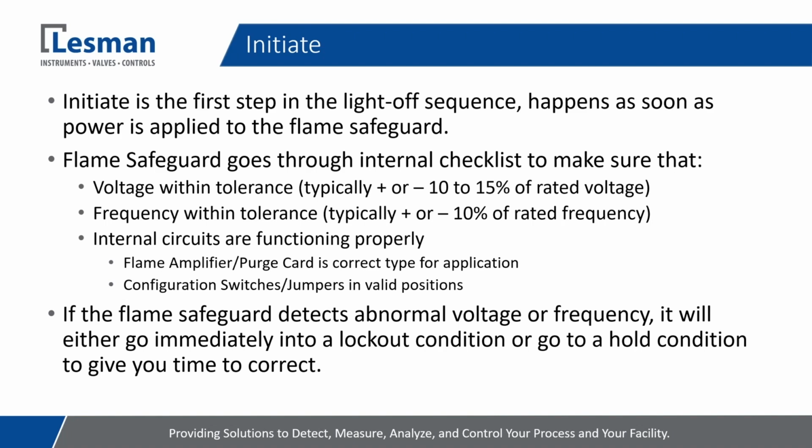With the Honeywell 7800 series, as well as some of the FireEye and the other flame safeguards, you have plug-in modules that you would insert to indicate either the type of flame detection or the behavior of the flame safeguard, and not every single combination of flame amplifier, flame safeguard and configuration jumpers is valid. So it just goes through and makes sure that everything that you have in your little mini flame safeguard system is correct and applicable for your application.